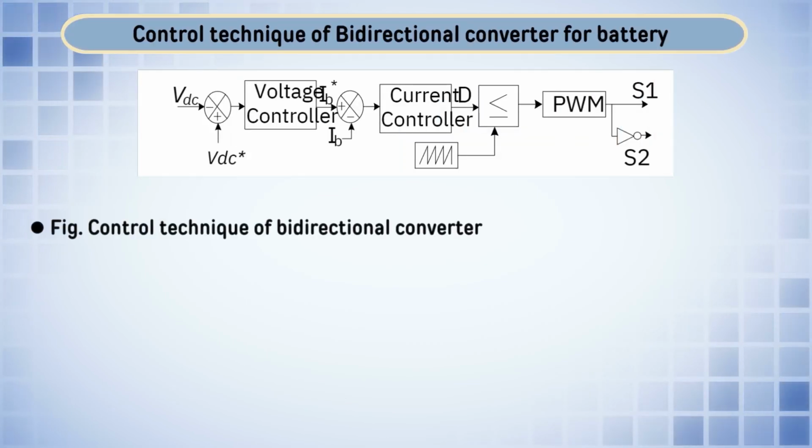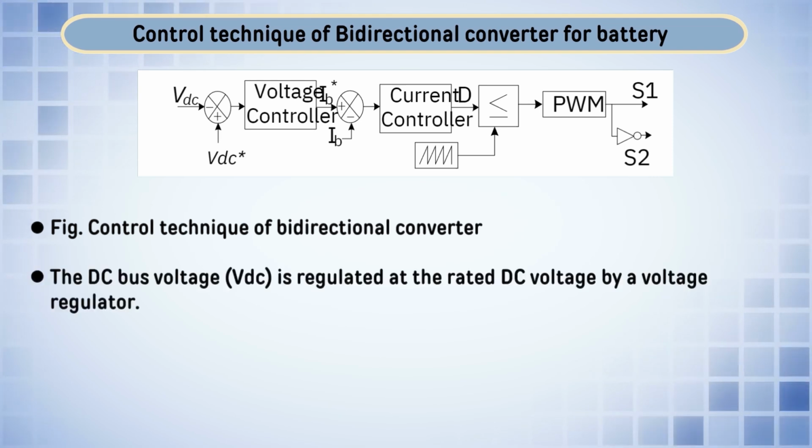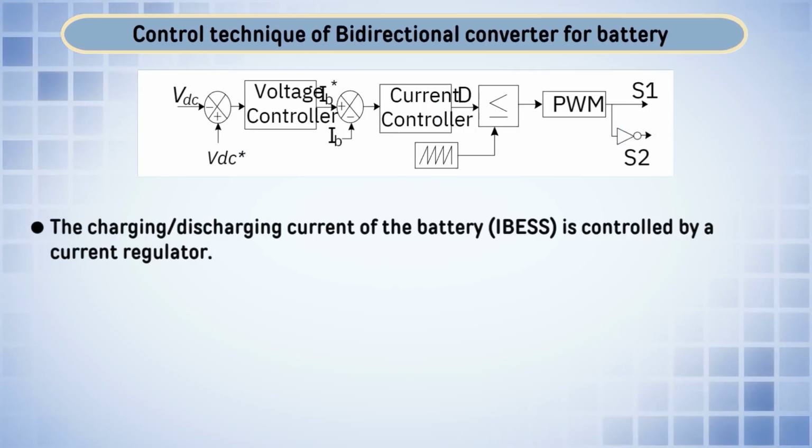And this is the cascaded PI control, where the voltage controller and current controller are PI controllers. The outer PI controller maintains the VDC, and the inner current controller regulates the battery current. So, we can control multi-spot EV because here the DC link voltage is regulated using a battery bank. However, we require charging for each EV. So, what do we have to do?